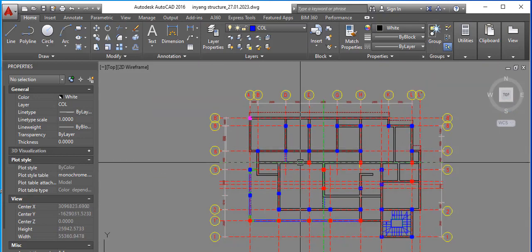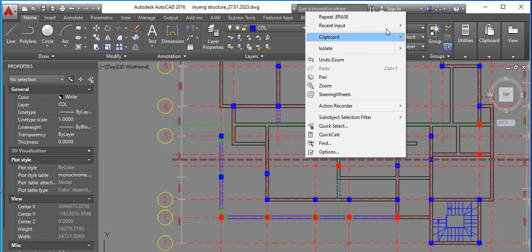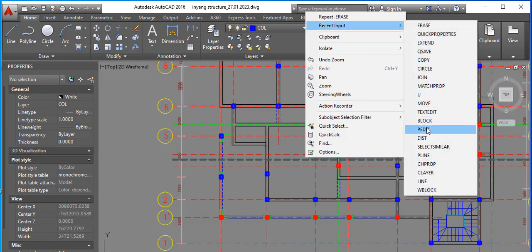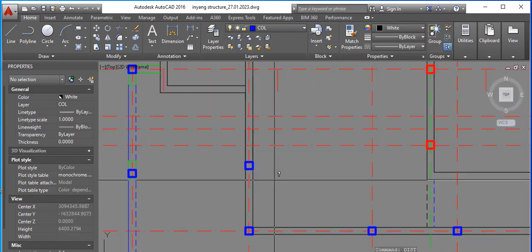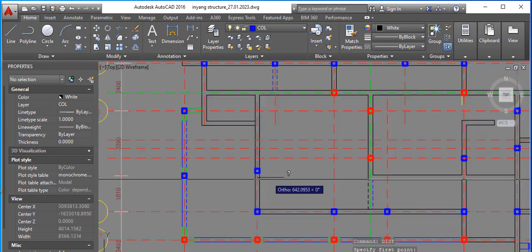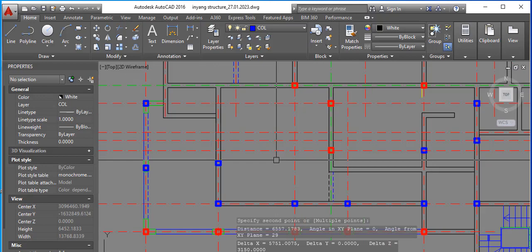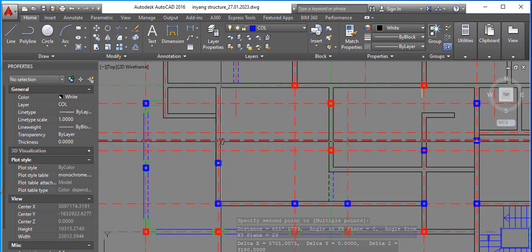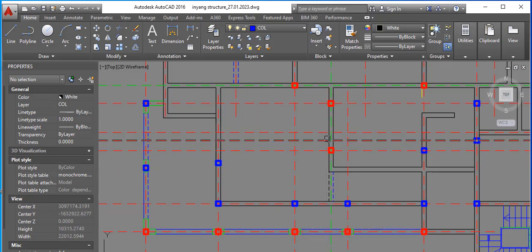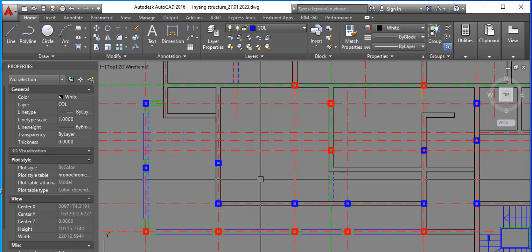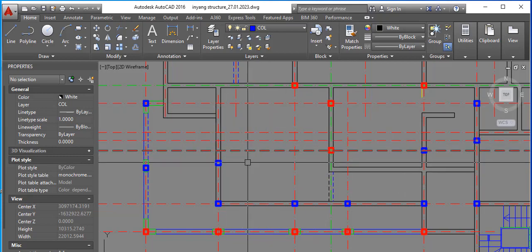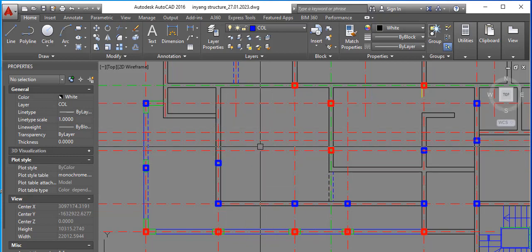So like all these that has very large span, so we could do this span from here to here. We're having 6 meters. So it's advisable you either break it this way, or you break it this way, depending on how you want to lay your trusses.